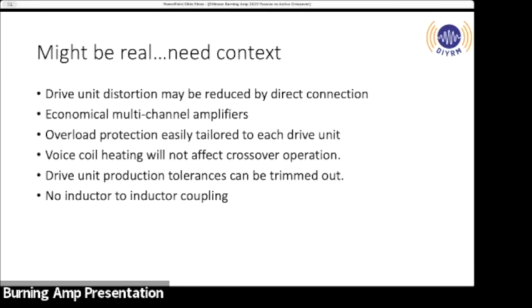Okay? And the coupling mechanism was between the inductor of the woofer low pass and the tweeter high pass. Because the tweeter crossover has shorted out, and no sound can be played out of the resistor, right? And I just kept cranking up the sound until I heard sound coming out of the tweeter. Shut everything off, reconnected the woofer, reconnected the tweeter, and saw how loud I was playing it. And I blew up the tweeter instantly.